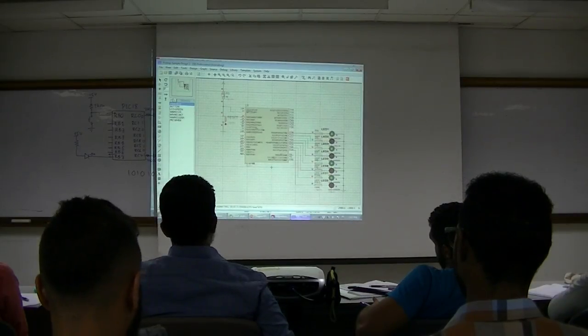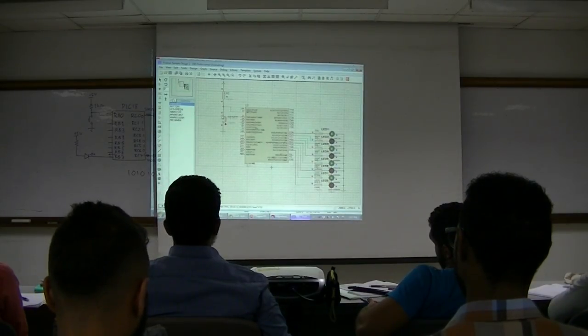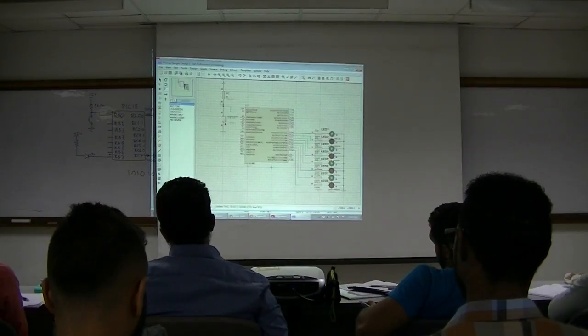That's why you see this small red box when you run a simulation. This box shows the logic. Red means logic 1, which is correct. Whenever I press this, it temporarily goes to logic 0, which means the PC automatically goes to the reset vector, which is address 00.